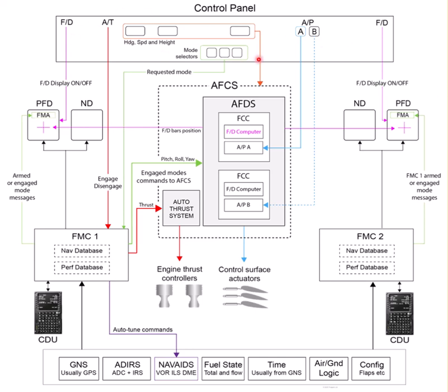We've got a control panel, we have full control over everything. We can switch off autopilots, we can switch off the flight director, we can disable modes anytime we want to. We can intervene, we can go into altitude hold, heading hold, whatever it is we want to do. But it's very important that we monitor the FMA, make sure that the engaged modes are what we want, that we monitor on the navigation display our route, not only laterally but vertically. So we may need to be checking on the CDU, we may need to be looking at the legs and seeing what our vertical profile is.